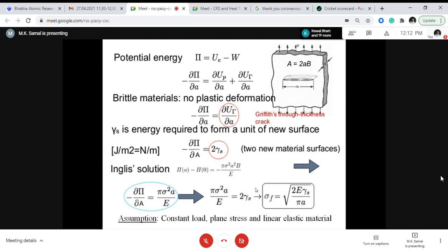We now have to calculate the stress intensity factor K1, which is sigma root pi, and instead of a, I will use a effective. That is my effective stress intensity factor, taking into account the correction for the plastic zone. So how do we calculate a effective, which is a plus RP? You must estimate the plastic zone size RP. There are different concepts for its estimation. One of them is Irwin's concept, which is a one-dimensional solution. I will also talk about some more one-dimensional and two-dimensional solutions, and some more elegant solutions for the plastic zone, which will help in estimating the effective stress intensity factor.